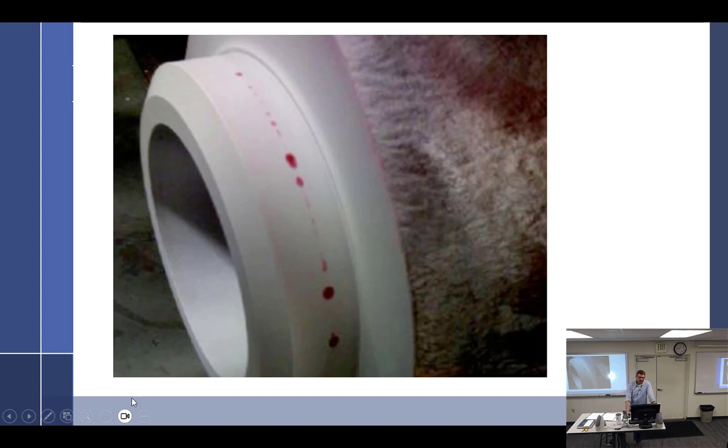This is a nice one right here that shows an actual discontinuity. But you can see because it's such a low sensitivity, it only comes out in very small spots instead of one continuous line. This could also be an indication you would get with a press fit part. Parts that are press fit together naturally have a crack in them because they're press fit. There's a seam. So that's what a seam would look like. So you have to determine, is that just a manufactured seam or not?